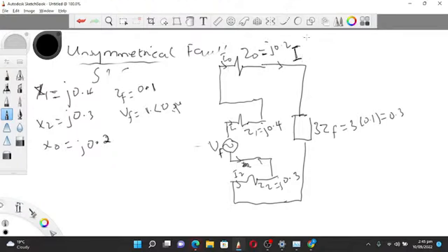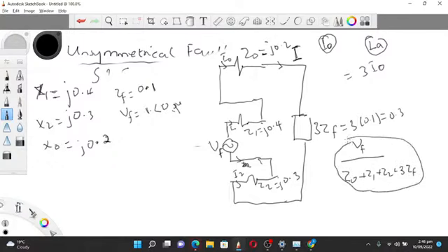we should know that when we get our I0, and then we want the fault current of IA, it should just be 3I0. So all you have to do from here is to do VF over Z0 plus Z1 plus Z2 plus 3ZF. Do this and you get your I0. Multiply by 3. That means if I want my fault current, straight away I'll do 3VF all over Z0 plus Z1 plus Z2 plus 3ZF.